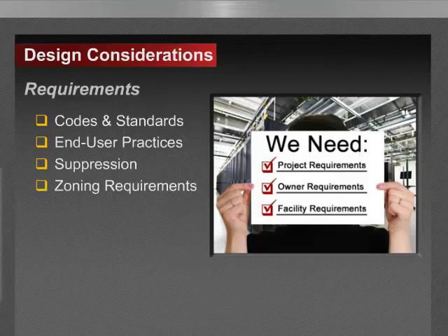So as we talk about requirements, we've got to consider these requirements as part of the design process. And so the designer must determine what local prescriptive codes and standards require, such as NFPA 72, NFPA 90A and B, for example, and what performance-based design codes require or recommend, such as NFPA 75 and 76, as an example, and what governing gaseous suppression codes require, such as NFPA 2001.